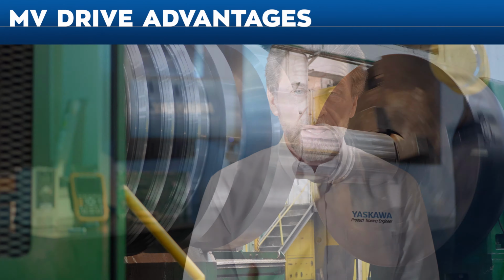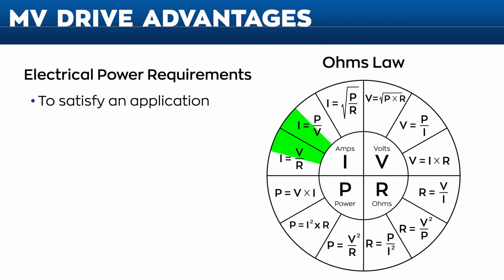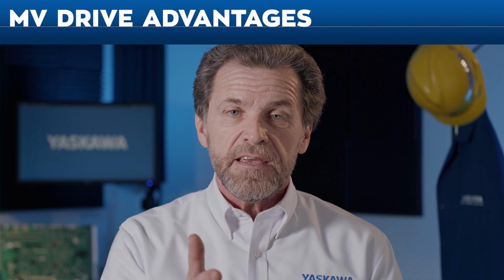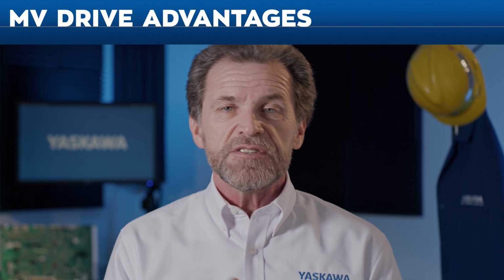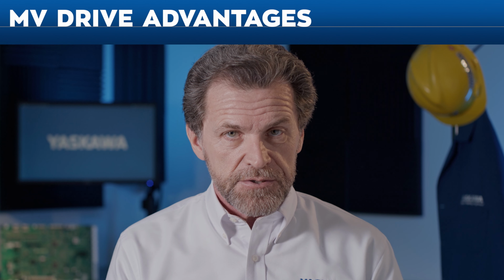In high power applications, MV drives have several advantageous characteristics. The primary advantage is reduced current. The electrical power that a motor requires to satisfy an application is determined by multiplying the motor voltage by the motor current. Power equals volts times amps. Increasing the voltage allows the same amount of mechanical power to be developed with fewer amps.